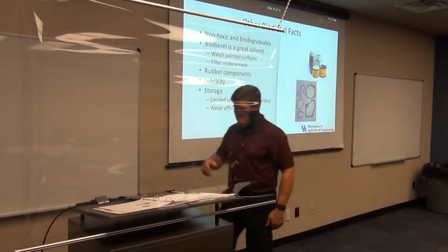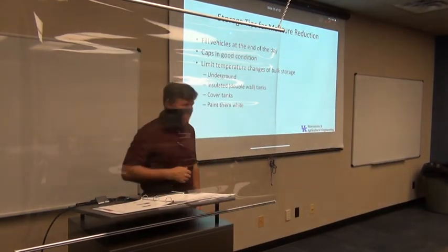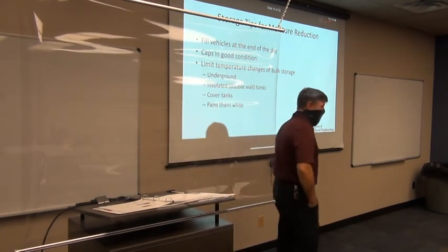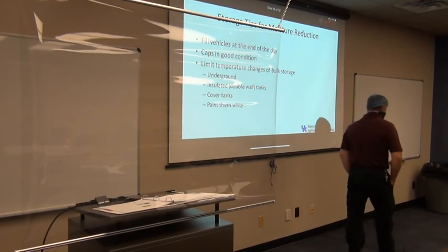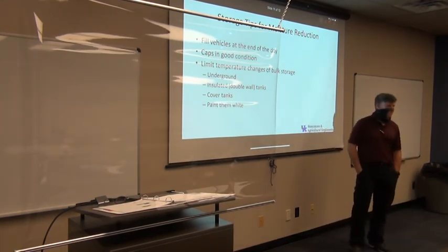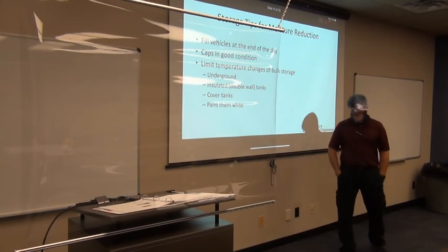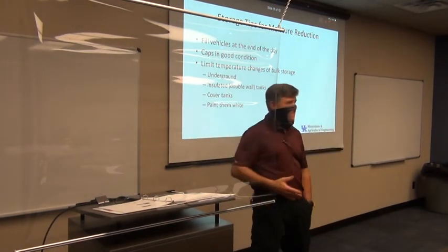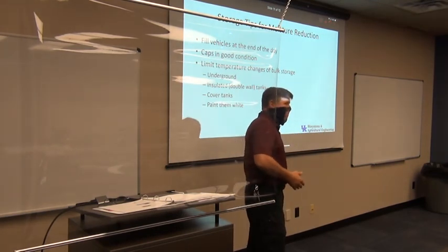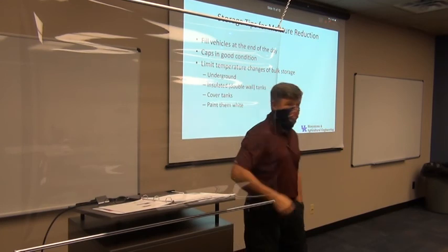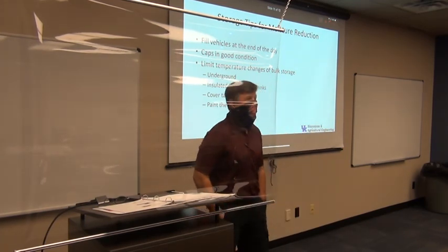All right, so some practical things. Here's some cool things for you to think about in terms of fuel and vehicles at the end of the day. If I want to keep moisture out of my fuel supply, this is what we tell farmers. You've been working out there all day long, it's hot, you're tired, you bring the vehicle back to the barn, you want to just park it and go home, but I'm saying nope. On the way in the driveway, stop and fill that tank up before you park the vehicle. Why?